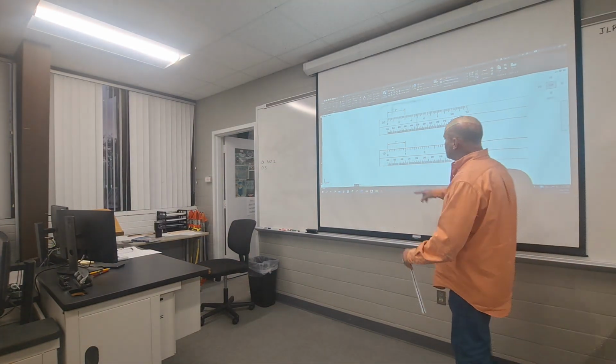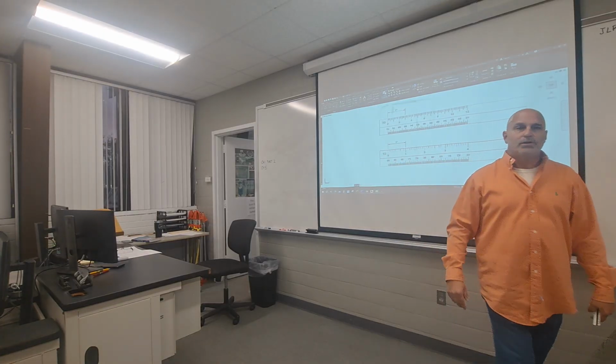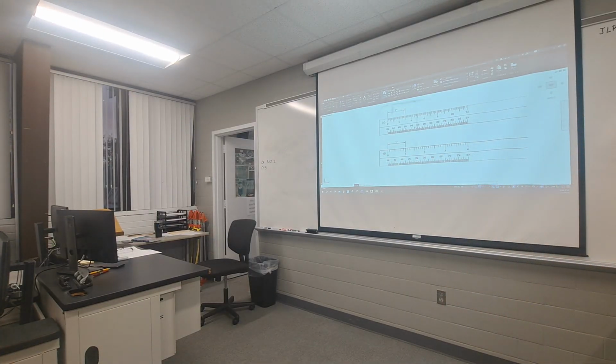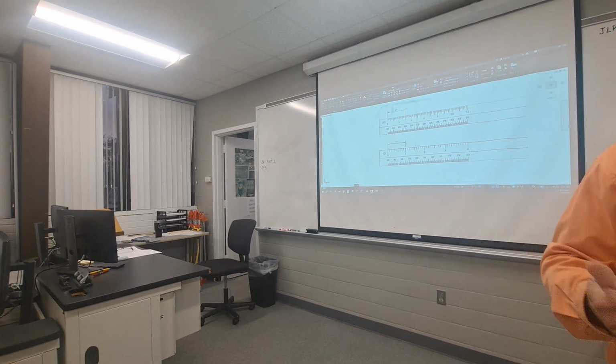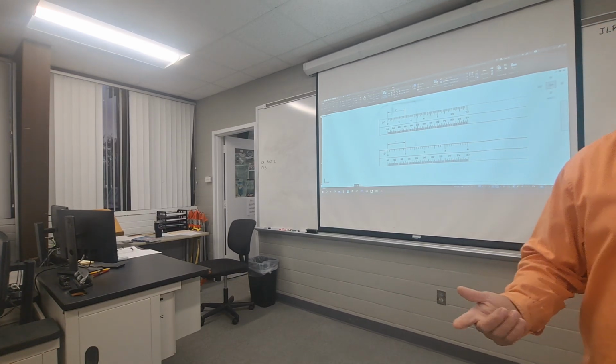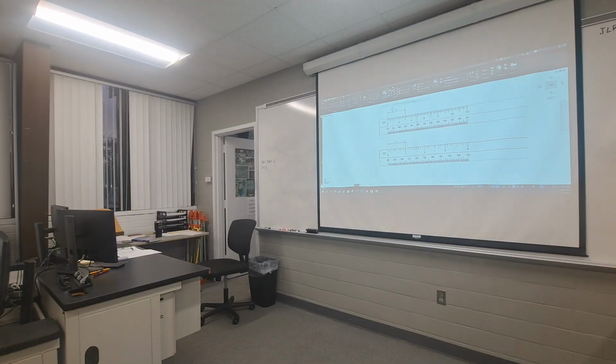So when you see this number 10, your civil scale, up until now you've been using architectural scales: 3/8 of an inch equals a foot, 1 inch equals a foot, 1 foot equals a foot. Every scale that you've been using, except for your diagram type classes like electrical and instrumentation where it was NTS, not to scale, ended with equals 1 foot dash 0 inches. In the engineering world, it's a different type of scaling.